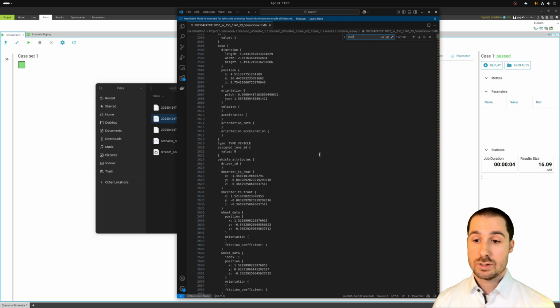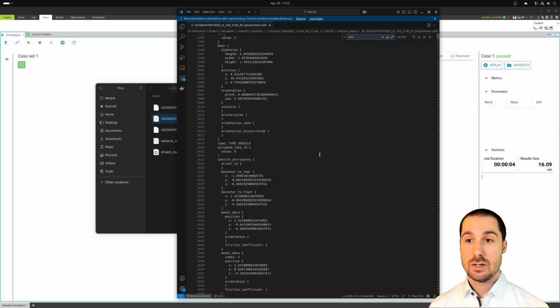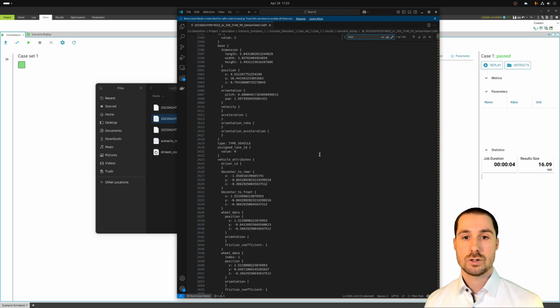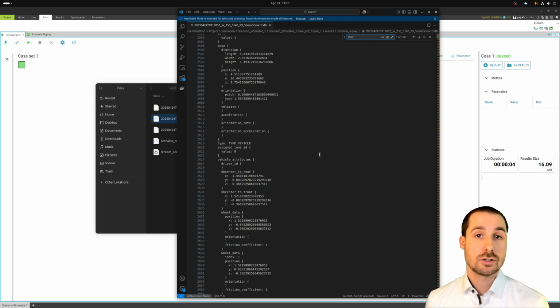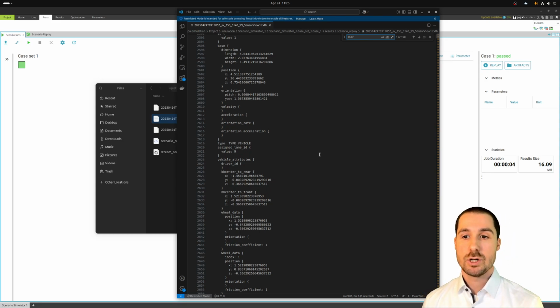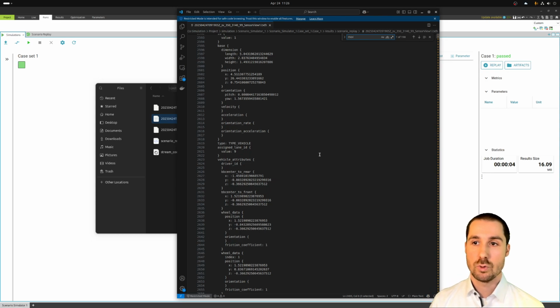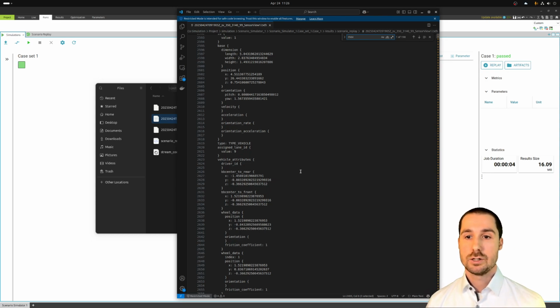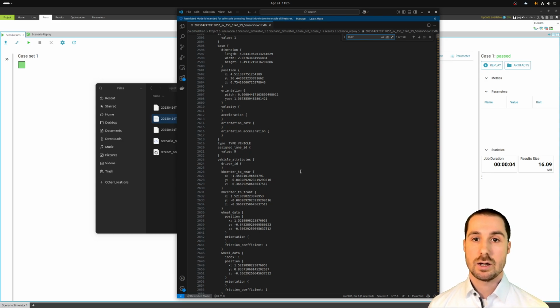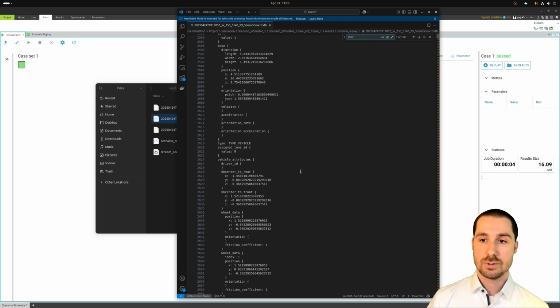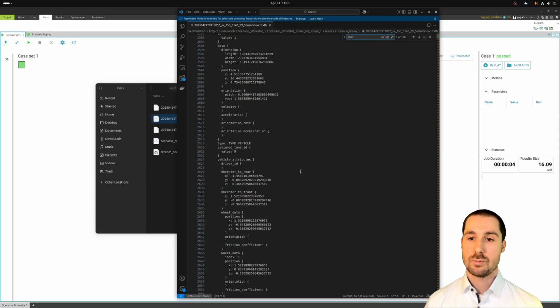And you can also use that to feed into new running simulations. So now that we've recorded the scenario, if we just want to play it again, or if we make changes to our sensor model, for example, and we just want to feed exactly the same sensor view in as before, we can store the sensor view, and then there are open source tools available to play that back. So there are trace file players available that read in a trace file and time step by time step play it back to the sensor model.